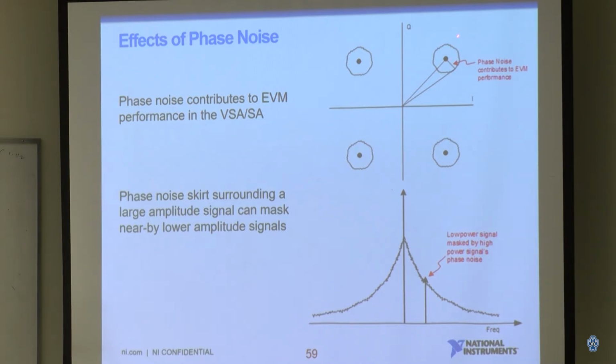you're not a solid dot in the middle. You're more like a cloud. So that means your signal has more error. Your signal amplitude or phase keeps changing, and it's not a single dot anymore, it's more like a cloud, so your EVM is degrading.